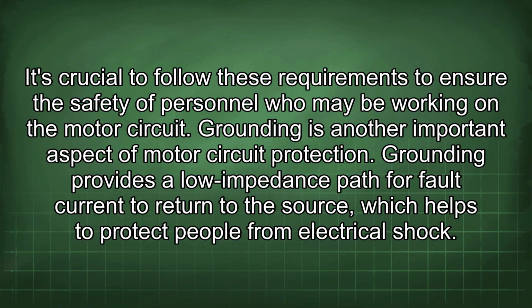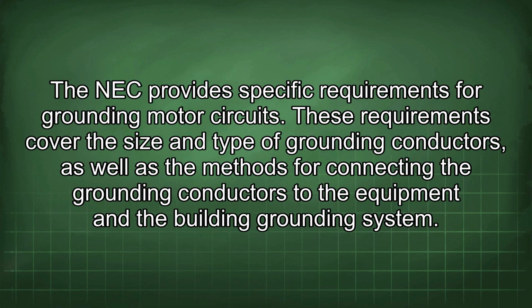Grounding is another important aspect of motor circuit protection. Grounding provides a low impedance path for fault current to return to the source, which helps to protect people from electrical shock. The NEC provides specific requirements for grounding motor circuits. These requirements cover the size and type of grounding conductors, as well as the methods for connecting the grounding conductors to the equipment and the building grounding system.